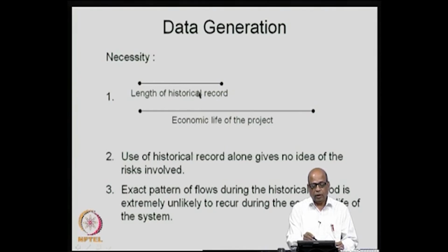So, you need to generate data for this economic life of the project, so that you will study the implications of this particular project. Let us say you want to look at the size of the reservoir, that is possible, or you want to look at, for a given particular size of the reservoir, how reliably you can meet the water supply for a given set of demands, and so on. So, they are all dependent on the flow record that you have, and therefore, using this flow record you would like to extend the data, the flow record itself, for the economic life of the project, which typically may be of the order of 100 years and so on.